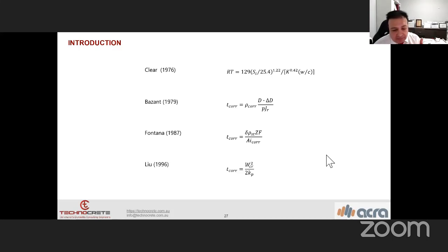Okay, because a strengthening design goes back to our analysis of the current condition of the structure. Then I cannot judge the strengthening design before having all those data which I mentioned, because we have to find out exactly what has happened to the structure, what is the current condition of the structure, what is the current load capacity of the structure, and then based on that we can design the strengthening. I mean, these are related, chained together. We cannot select only one link in order to investigate the whole. Then for the review of a strengthening design, I need the whole information. Okay. Yes.